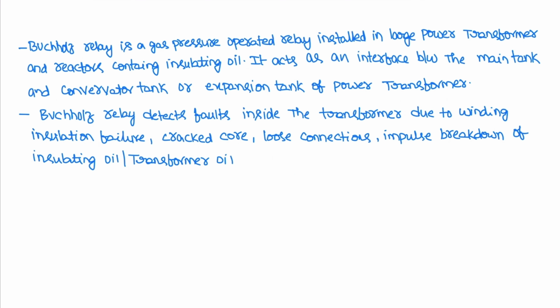So let us see some more points here. This Buchholz relay detects faults inside the transformer due to winding or insulation failure, faults due to cracked core, faults due to loose connections, and faults due to impulse breakdown of insulating oil or transformer oil. This relay acts as an interface between the main tank and conservator tank of the power transformer.